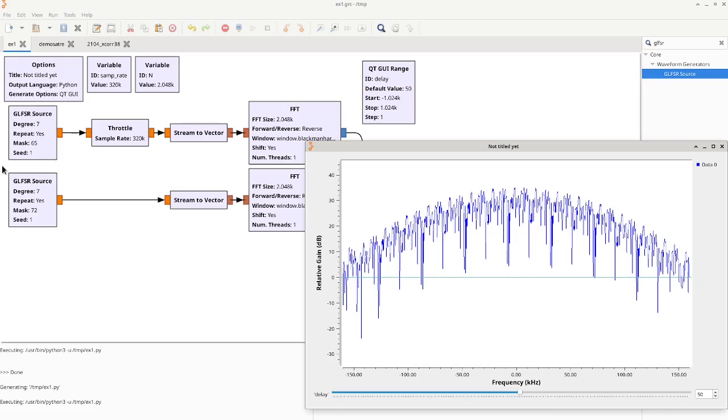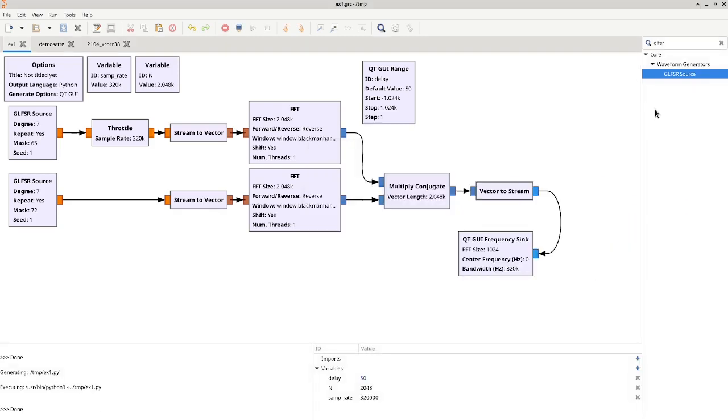Hence, if we run the sequence representing the gold code of the appropriate satellite, we will get correlation peaks repeated every sequence length, 1 millisecond in the case of GPS. If we encode on the ground a sequence that is representative of a satellite that is not broadcasting, then we will get no energy in the correlation. We thus have the means of spreading the spectrum in a reproducible way and easily described in an algorithm through the Galois linear feedback shift register, only requiring the location of the taps and the register length.